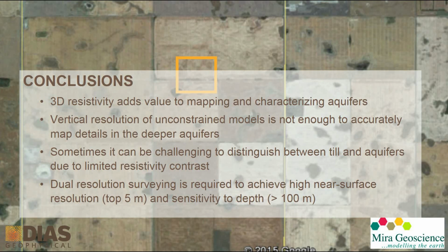My second question is, with your new system, you can actually sample quite rapidly. Is that true? In other words, can you get the early time channels after you switch off so that you might consider using your data in a time domain EM system? Yeah, right now our focus is on IP resistivity surveys, so our sampling rate is between 200 and 300 samples per second, but we're going to be upping that shortly. But no, there's nothing to stop the system from being used to record EM data or whatever. It's just a matter of the sensors.